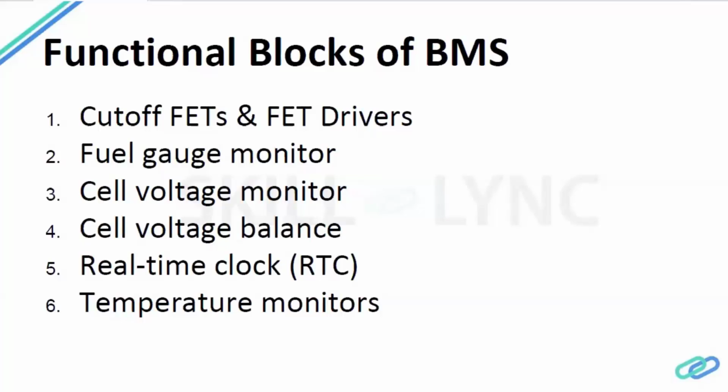And there would be some voltage balancing, because you might be using more than 30 or 40 lithium ion cells, so there is a possibility that one cell will have 4.5 volt while another will have 4.3 or 4.4 volt. So there would be a certain difference between the capacity of each cell. We have to balance the cell voltage using a circuit, like active balancing or passive balancing.